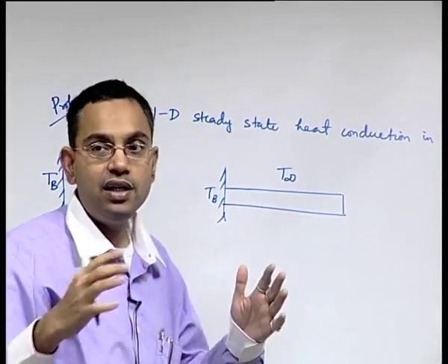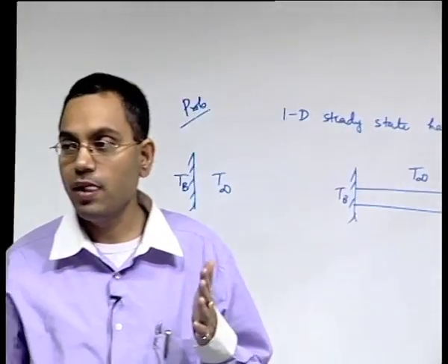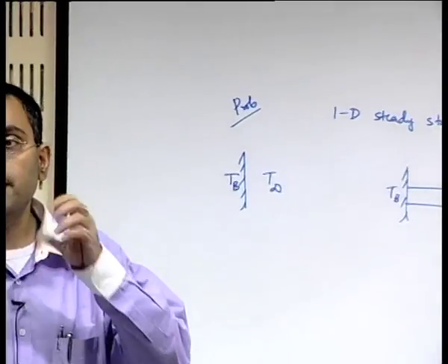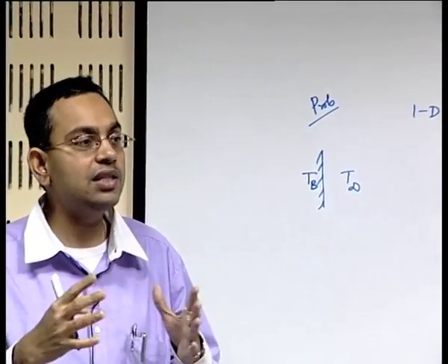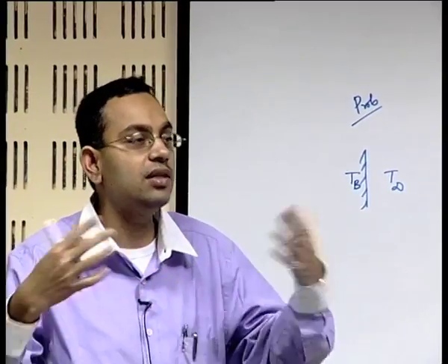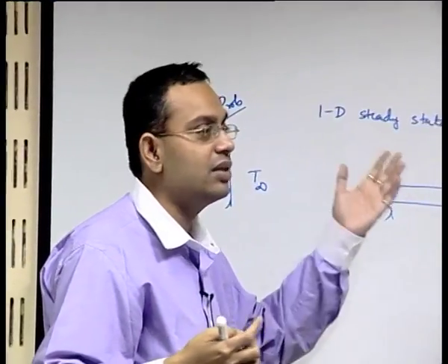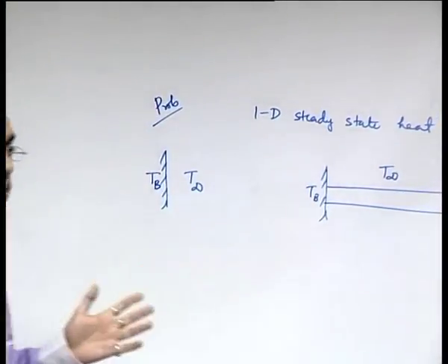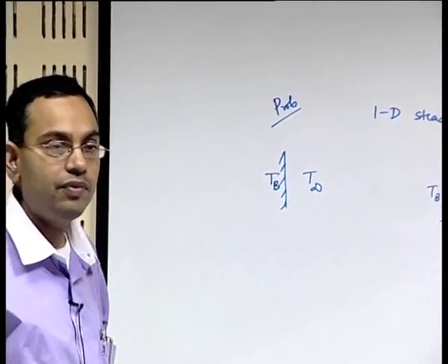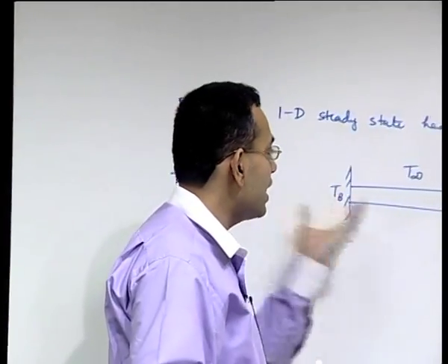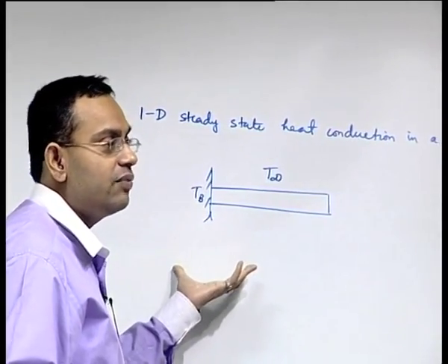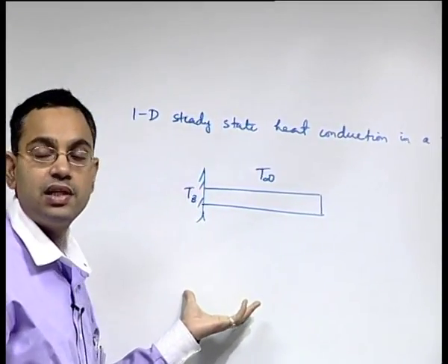So on one hand you are adding surface area, so that is augmenting heat transfer. On the other hand you are reducing the temperature difference, which is the driving potential for heat transfer. So the combination, the fin may be effective or ineffective depending on whether the combination is good as a design or the design is a bad one. We will not go into the details of that one, but this is just to give you a common perspective of whether a fin can be effective or not. Now let us say that we are interested to write a control volume balance for a fin, derive a governing differential equation and write a finite volume discretization based on that one.